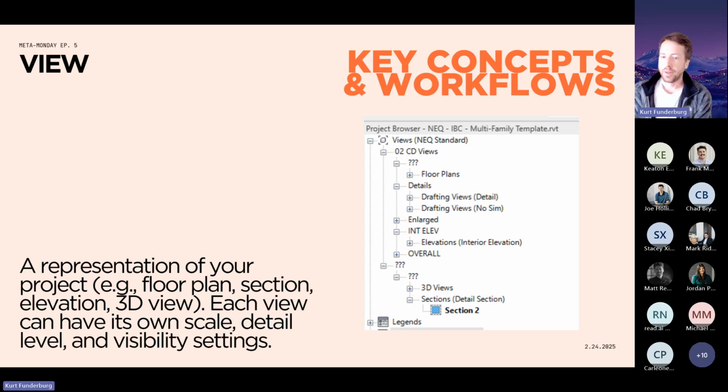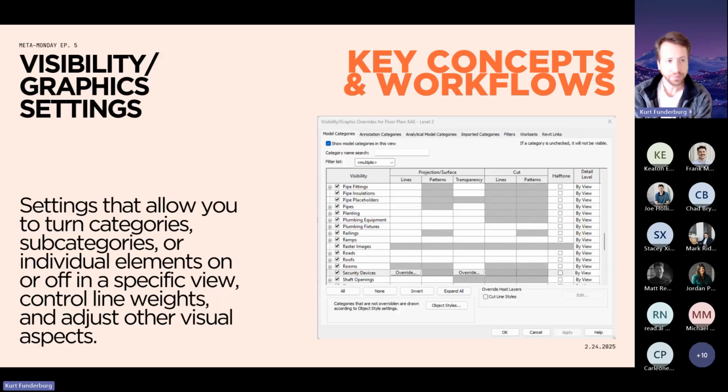So with views, especially for new users, don't be afraid to create a new view. You can create thousands of views and then you can easily, quickly delete all of them. So be comfortable with making your own views. It's all about viewing and seeing more in Revit. The fact that we don't have to draw or draft a section to understand what I just modeled is sort of the keystone of what Revit's getting at, that we don't have to spend the time drafting something that we already know and already have drawn in elevation.